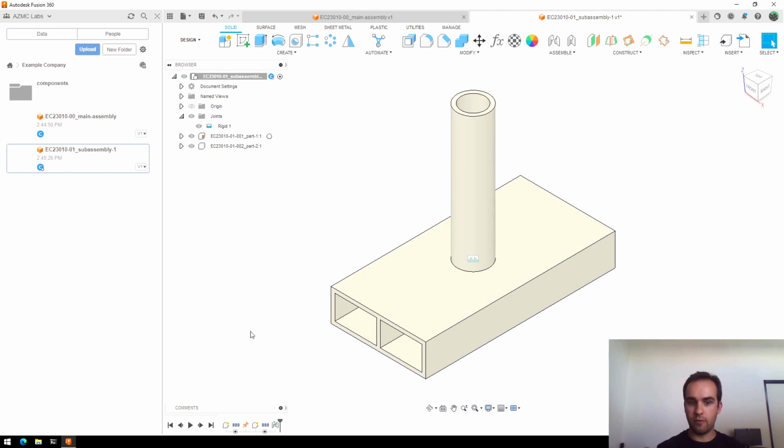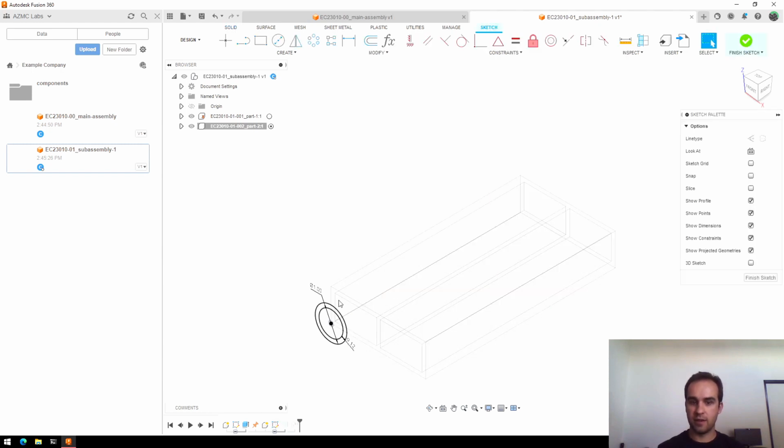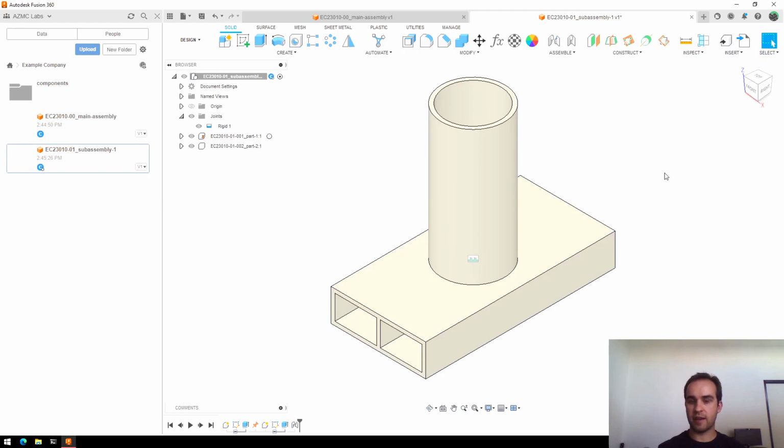And then when you're working on this file in the future, if you want to make a change, you should always go back to your existing sketches and operations, which you can double click on, and modify things there rather than adding new operations to ensure that your whole timeline updates cleanly and your parts are defined very precisely with where they are and what size they are.